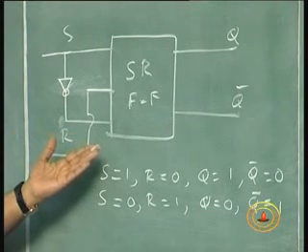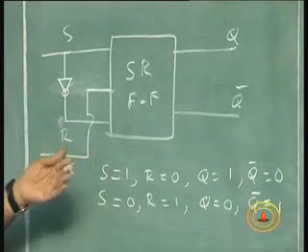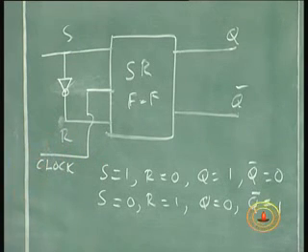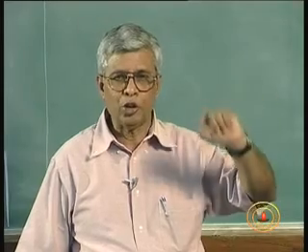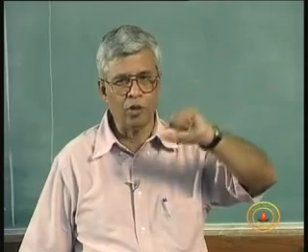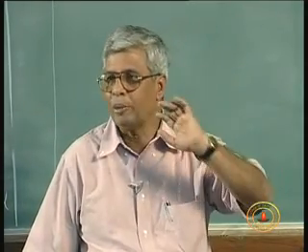Now I can use the clock for the memory operation. For a memory operation, earlier we had to put a 0 0 for memory. Once I put an input 1 0, then remove it and put 0 0 for memory, or put a 0 1 and remove it, put 0 0 for memory. Now there is no need to put a separate 0 0 for memory.